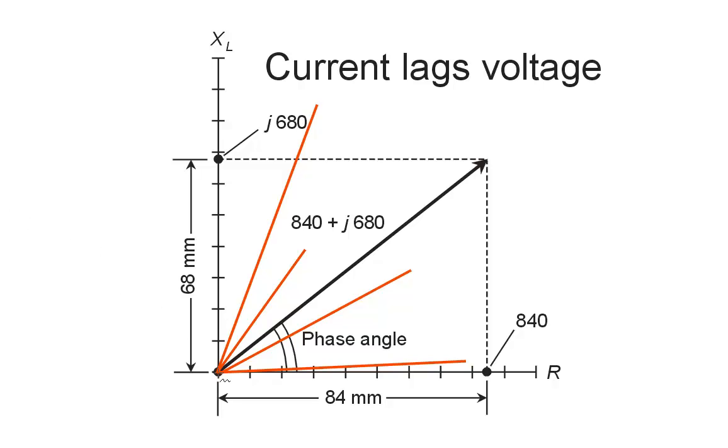In fact, if the reactance, imaginary inductive reactance, is many, many times the resistance, thousands of times, then we'll get an angle of lag just about 90 degrees, and we'll get just about a vector that goes just about up along this vertical axis, like, well, almost there, like that.